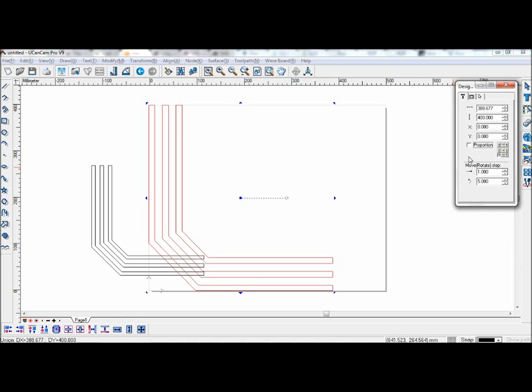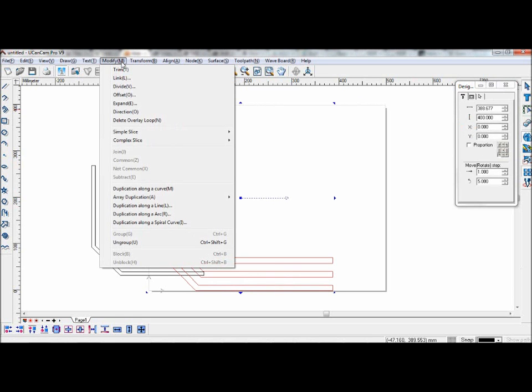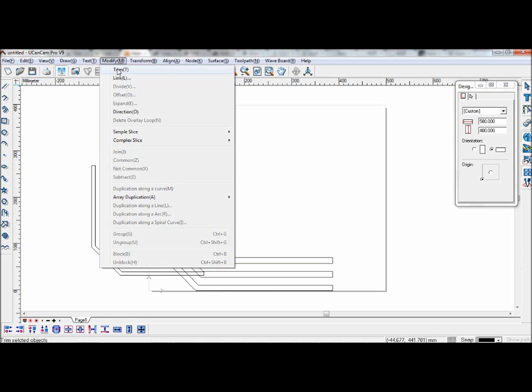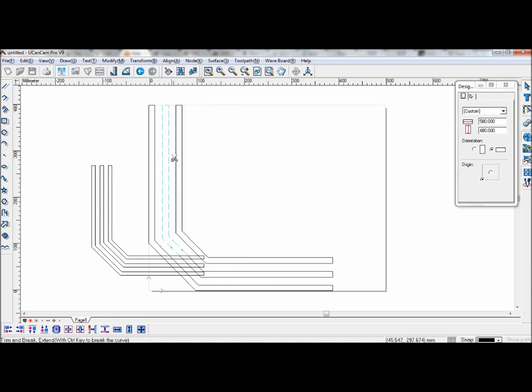To modify these graphs, select them, go to Modify, and you have another list to modify these graphs. Go to Modify and Trim. And to delete some of the lines, hover your mouse over the part where you wish to delete the lines, and when you see it has become the blue dotted line and the scissors, left click and you will trim the objects.